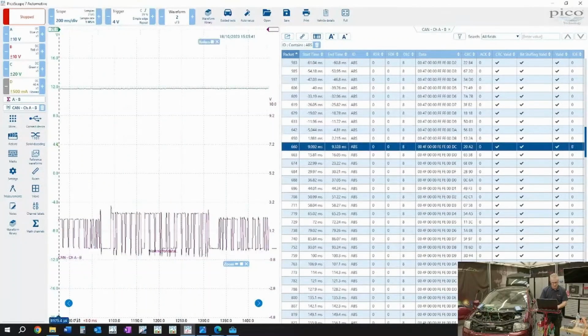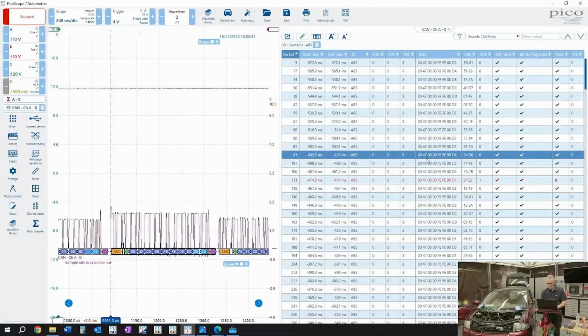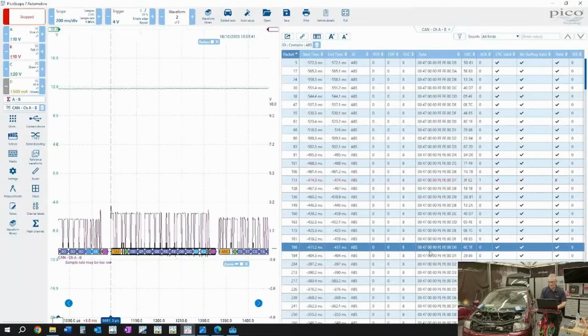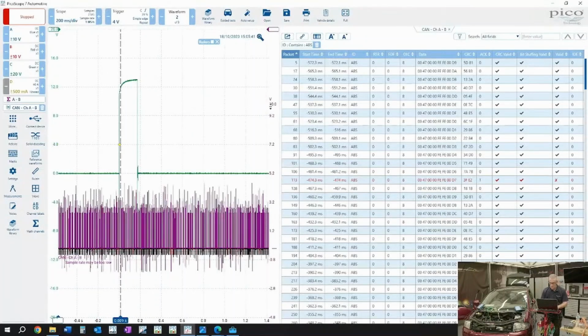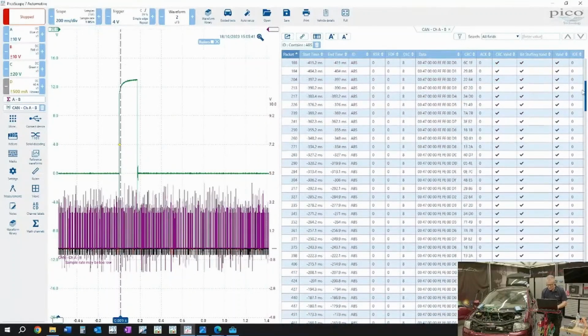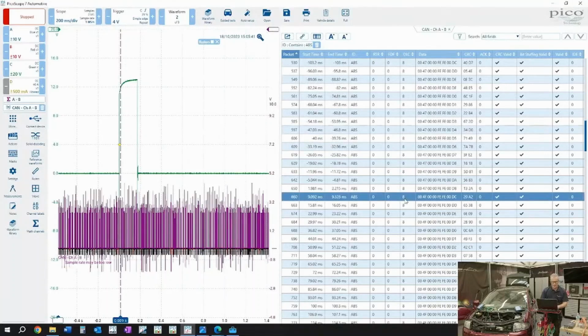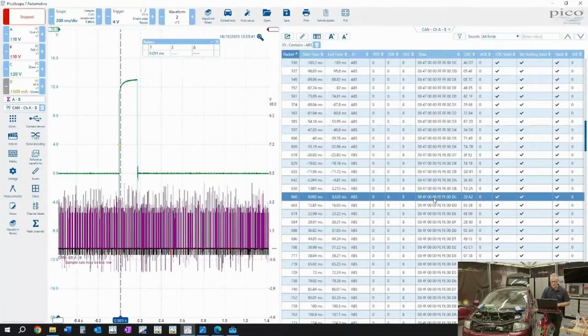So I'm going to place this ruler here. Where were we? 1A0 4F. And come back out of the zoom. So my packet number, let me find that again. I've lost where I was. So from 47 to 4F, 47 to 4F was 9.3, yeah, just over 9. 47 to 4F, 9.328 milliseconds after the trigger.